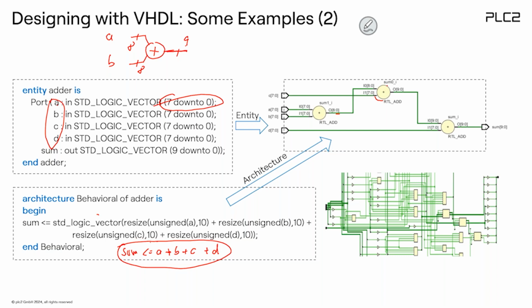That would be the correct 9-bit, but don't expect this because VHDL is not doing this. So this means you have to explicitly define that the output will have a bit growth of 1. If you add 2 8-bit values, you will get a 9, but you have to say this. And in order to do this, what you have to do is something like this.